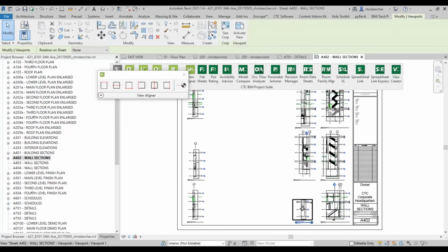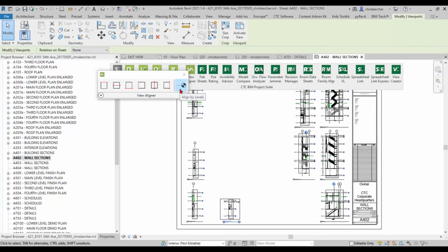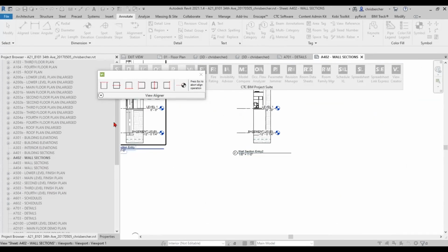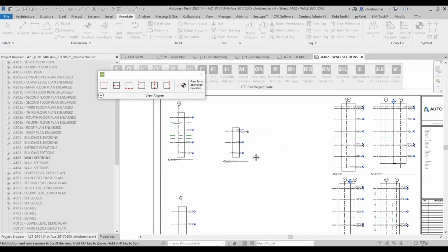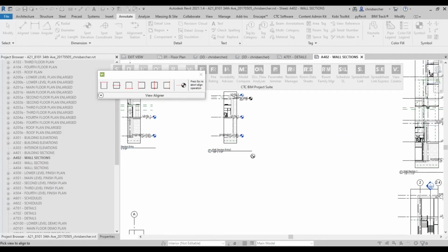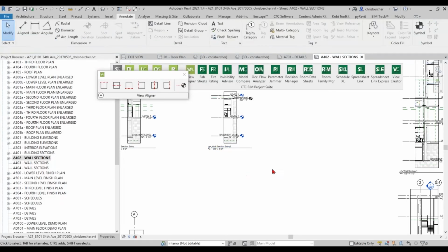Went too far. So I want to take this view, but instead of it being down here, I want to bring it up top. So I have the ability to align by levels or by bottom edge, top edge. But if I wanted to do by level, I can do that by grabbing this view and then grab this view. And it's going to automatically for me align based on level 1, right? So even if level 1 wasn't present in this view, it still would have aligned it based off that level, right? And now I notice my view titles are a little off, but I can clean those up myself. So get that pulled up. Now we're good to go.